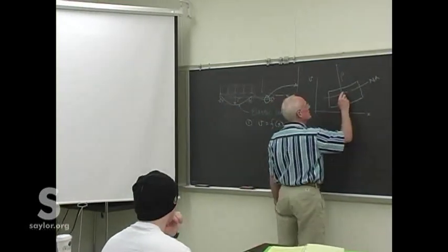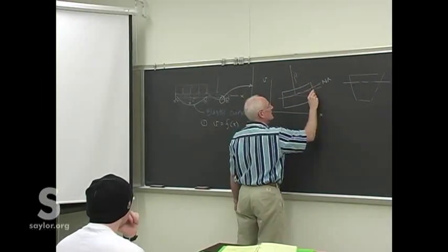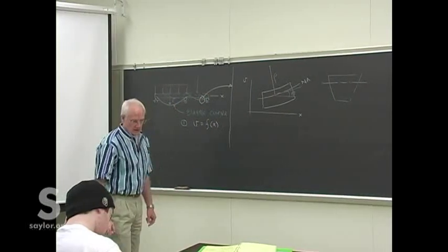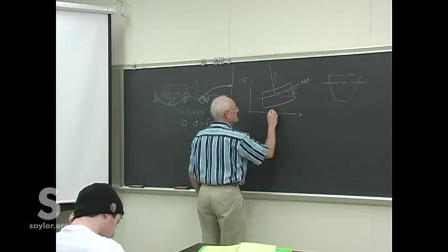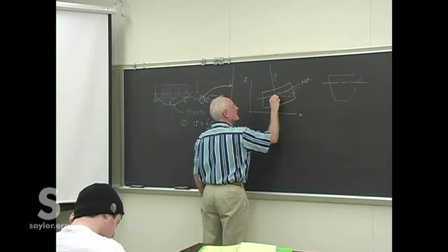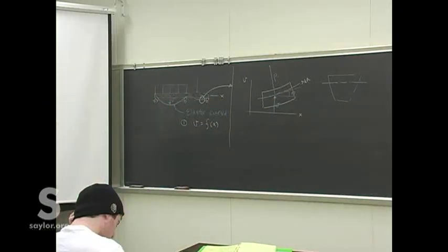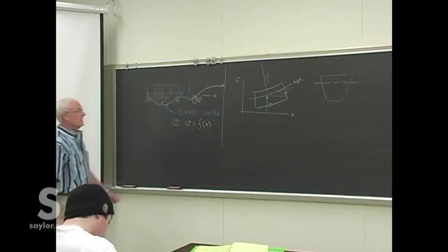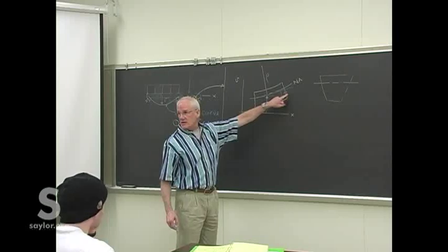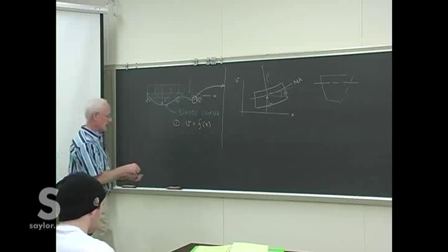So we've got the curvature there. At that same spot, we've got some slope to the curve of that place, and we'll call that theta. So we're bringing together this deflection from the neutral axis, V, and we're trying to find the equation for that as we go along the beam. You can see that fairly obviously the curvature and the slope also change with x as we go along, and all of these things are going to be related.